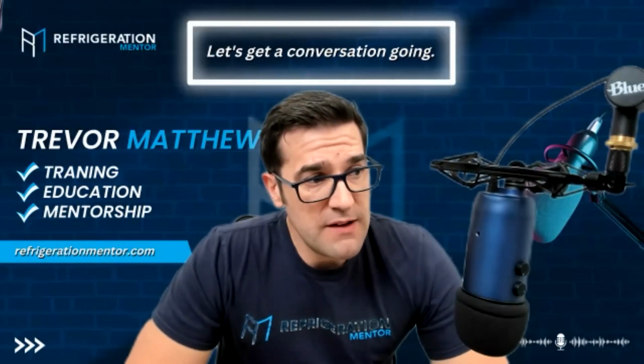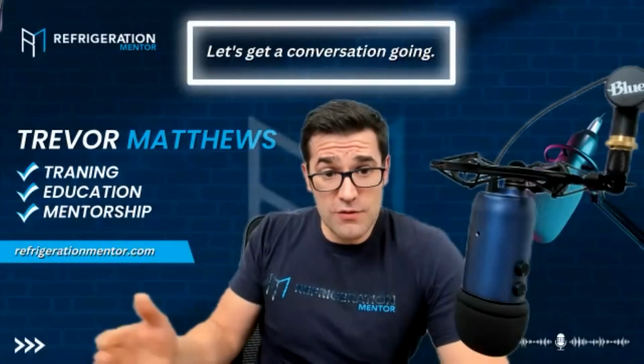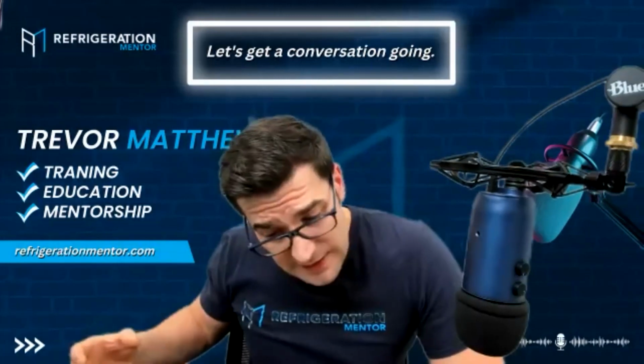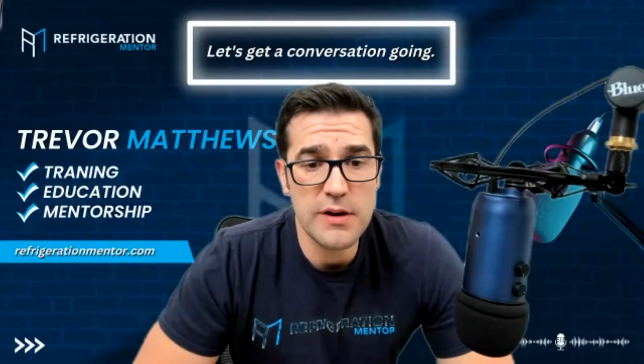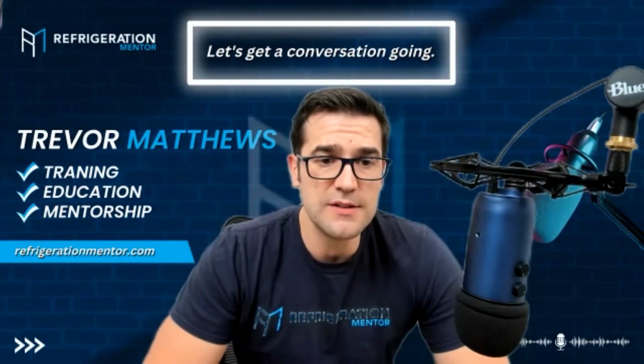Another thing, if you have a variable speed drive on it, maybe, and you're slowing down and you're running real slow, and you get no mass flow coming back. We're talking about, you need that cool gas coming back. Metering device is another one. You might have the right amount of refrigerant, but if you got a plugged screen, what's that going to cause, right? Don't get in that gas. It's restricting. Cool. Yeah. So there's many, many different things.